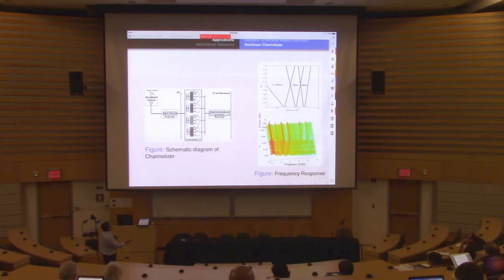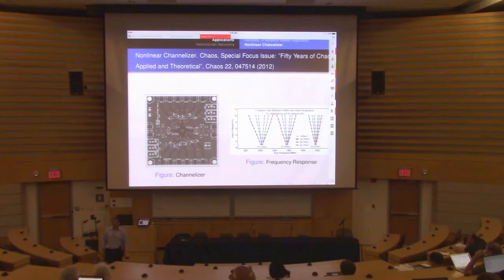Changing the IC component basically shifts the system from one Arnold tongue to the next Arnold tongue. So the system can actually lock into a signal. This is the actual circuit realization. These are the different channels for different values of IC. So IC controls the actual frequency location of the Arnold tongues, and the IG parameter basically opens or closes the channel in order to filter out noise, or if there are multiple signals coming in at the same time.